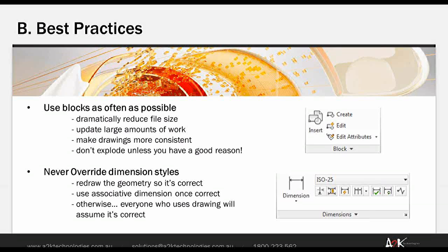I've come across issues in the past where clients have actually documented concrete beams to go on bridges, and someone's done some overrides on the dimensions, and they've come back and everything doesn't fit correctly because of that reason. It may have been 15 mils longer than what it should have been, or 20 mils longer. So very important. It eliminates mistakes. People can see straight away what's going on, and I find that when people get busy, they make assumptions, and quite often the mistake is not picked up until it's too late.